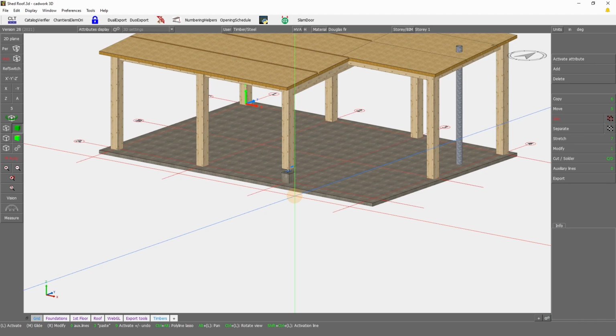We could also achieve this copy by simply copying this element to the rest of the posts, but the container block allows you to create a link between these assemblies, so that you are able to modify one and modify all the linked ones. So we are going to have a look at this new element and how to use it properly.